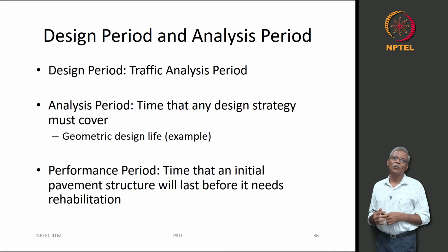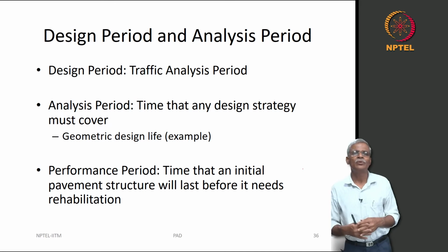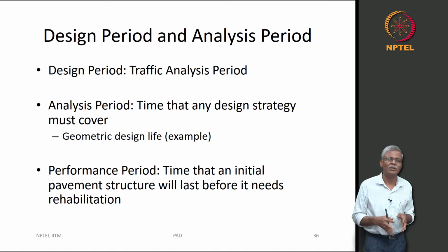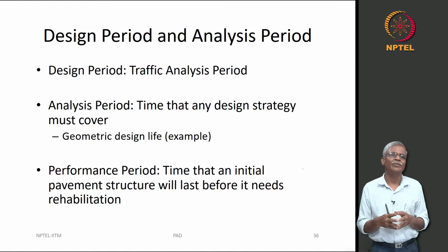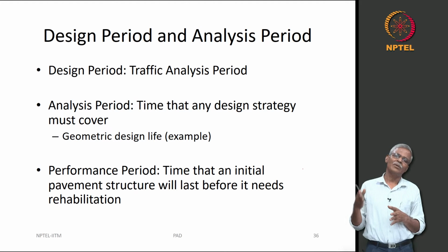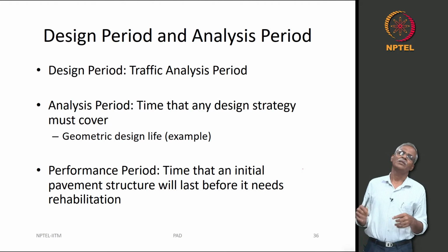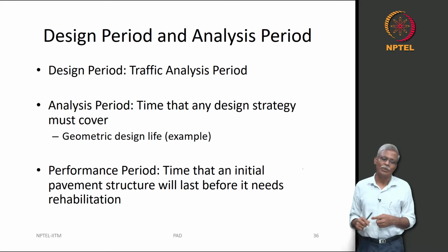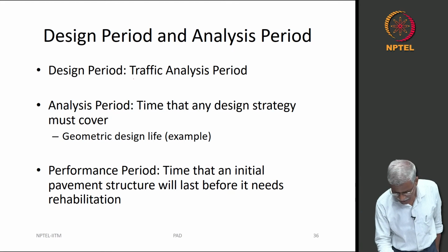Okay. So, now we need to take a recap of the design period and the analysis period, because these kinds of definitions and classifications are very important as far as the South African manual is concerned. So, what exactly is a design period? It is the traffic analysis period.